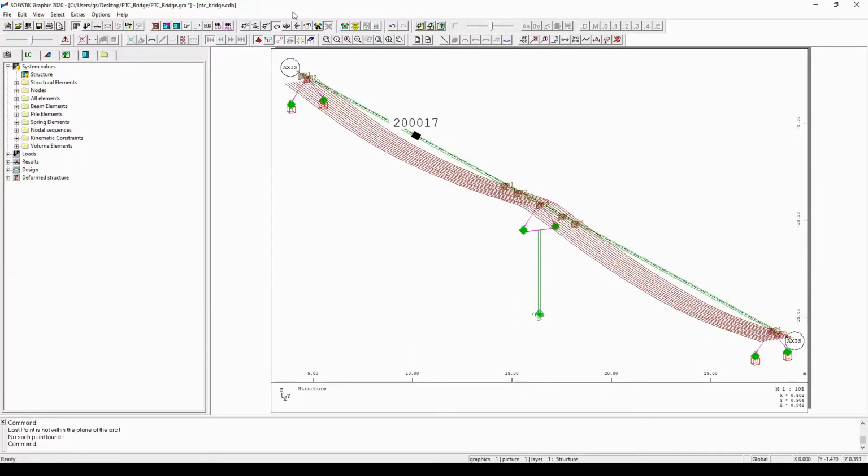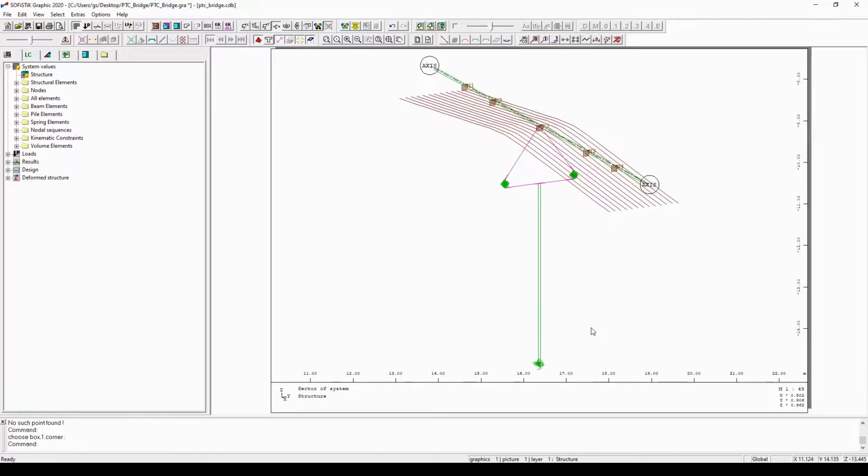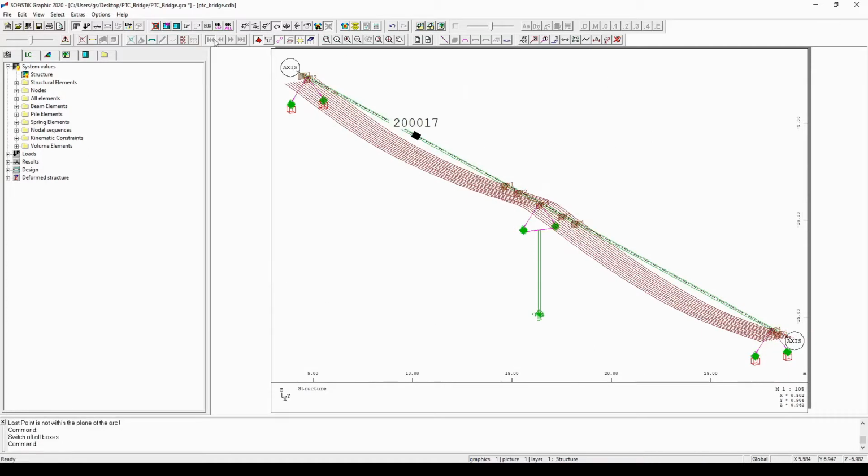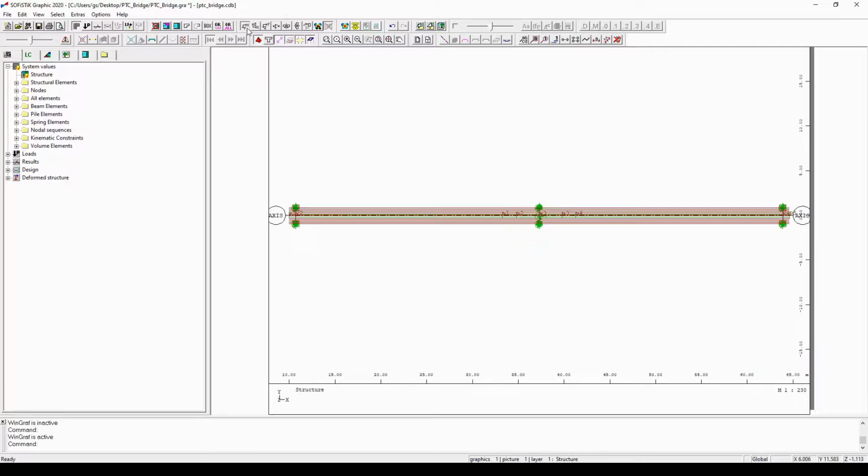The other two important commands that I would like to present are the so-called box and the structure limits. With the help of the box command, basically you can cut out a part of the structure with a box. And if I now click on the structure limits, then my whole structure will be presented once more. Now let us click on the top view, the XY view, and try to imagine the before mentioned very complex structure of ours. The workflow I wanted to show to you is as follows.